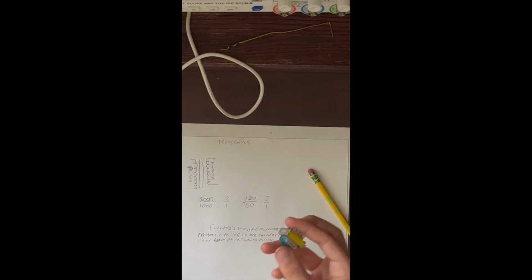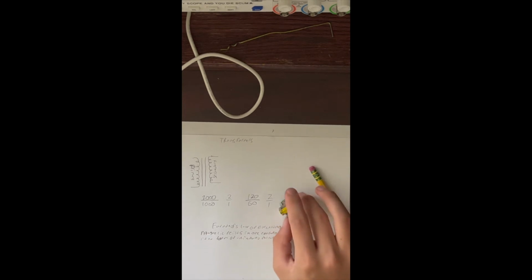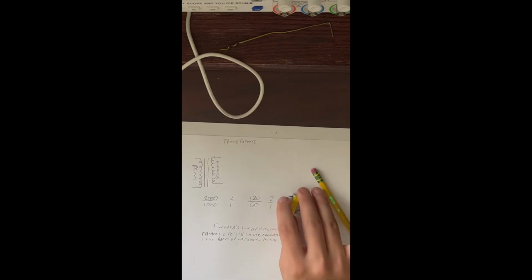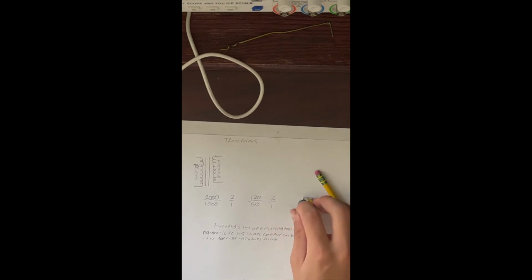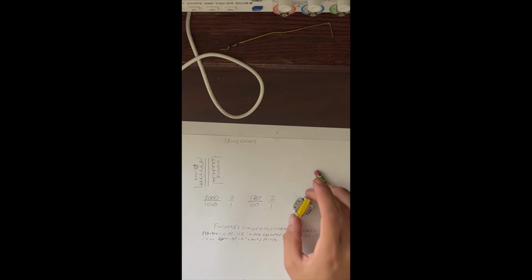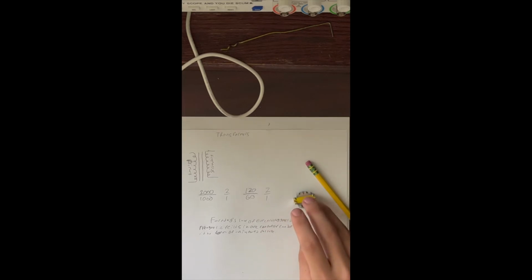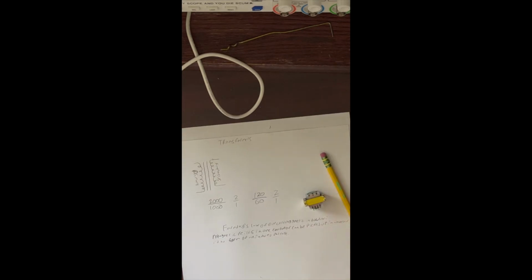We still get our magnetic fields out of the inductor no matter what. But the iron core helps to strengthen those magnetic fields and helps the secondary pick it up a little bit better. Because without that, the more current we put in, the stronger the magnetic field is going to get.